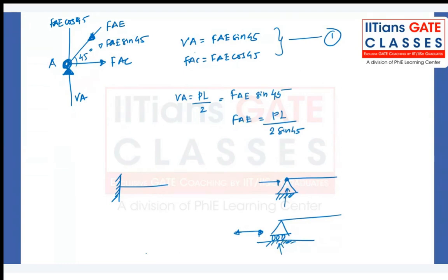And here, it is like a pin joint, right? These beams can rotate about the joint, so there we don't have any moment. But in the fixed support, we are restricting the vertical direction, the horizontal direction, and we are not allowing it to rotate like a pin. So it will have all these reactions, not only vertical and horizontal, but also the moment. Is this concept clear to you, Sham? Yes, sir.